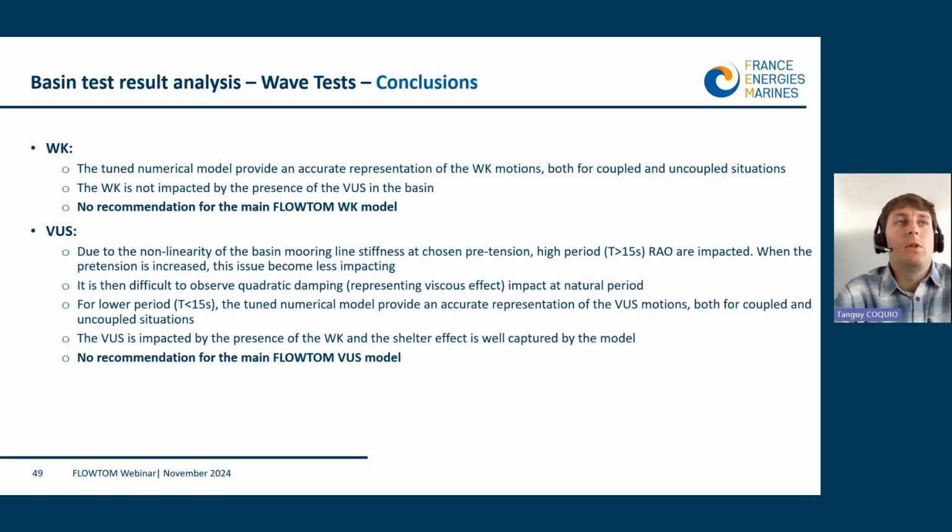For the semi-submersible floater, due to the non-linearity of the basin mooring line, as I presented in the slide before, the representation of RAO for high periods, meaning periods above 15 seconds, is impacted. So this is something to be considered in this study, that we cannot be safe with what is represented above 15 seconds.